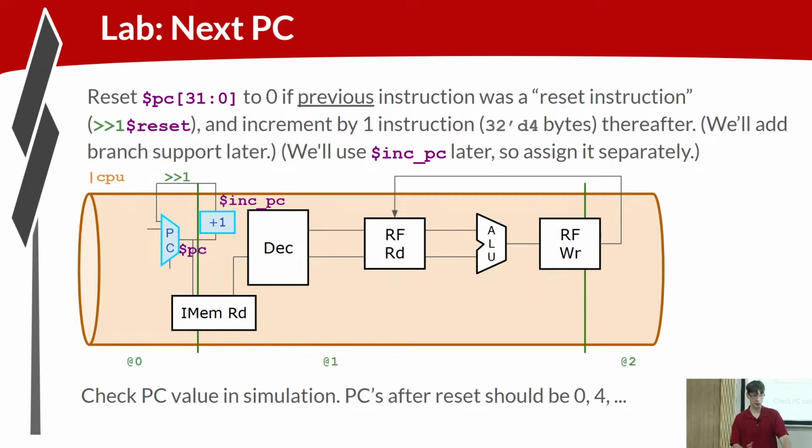So remember, this is set up with a reset pipe signal, right, to, as we talked about before, consistently reset throughout the pipeline. So we can view the instructions as either reset instructions that are clearing things out or non-reset instructions. So when we first deassert the reset, we're going to get the first non-reset instruction going through our pipeline. That one needs a 0.